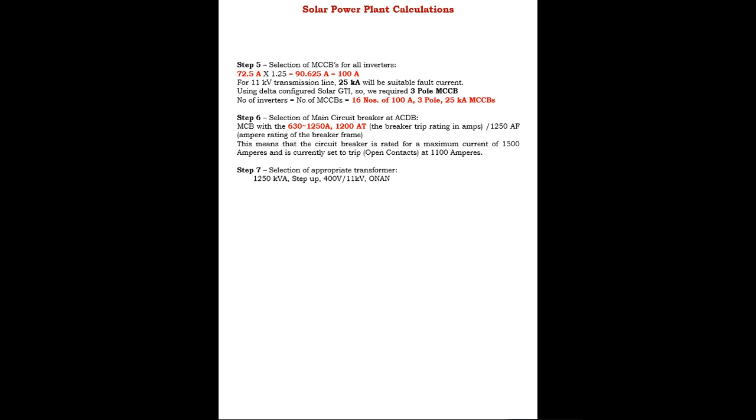In the initial part of this session I tried to talk about the 1 megawatt power plant here by our institute. So over here we are having the final transformer of 1250. So the thing is like that, we are having a 4-string inverter, each of 250 kilowatt. Each string inverter is 250 kVA. If you oversize accordingly, suppose 1.4 times you can oversize, so it could be a 325 or 350 kVA. It is connected with the individual transformer of the same capacity, but the main transformer is 1250 kVA.